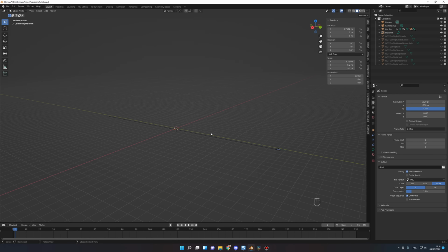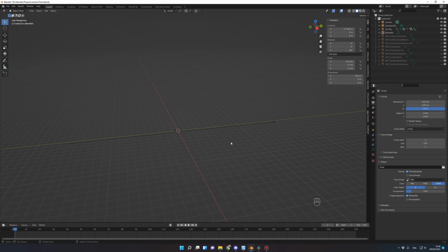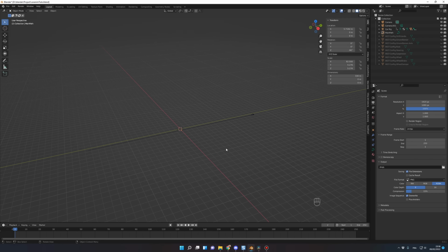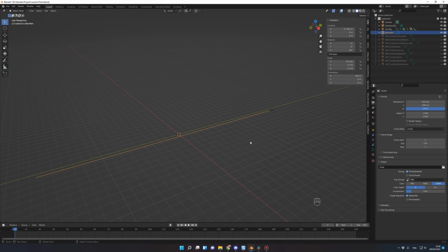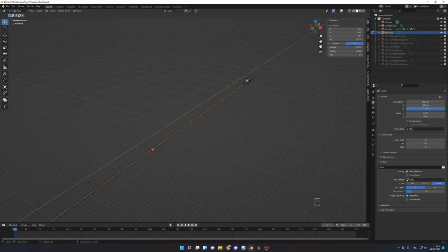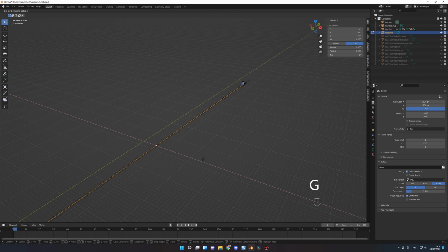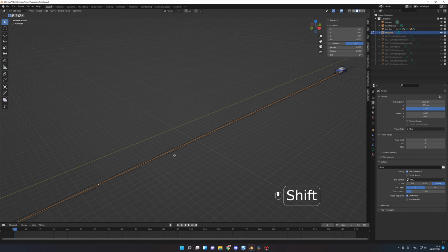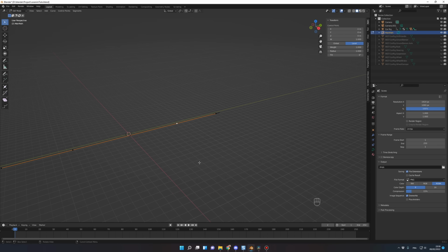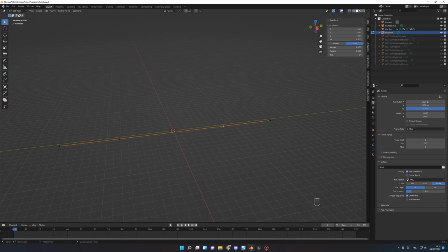The way we scale our path is not good, but I wanted to do it like that to show you a common issue that people have. If I select my path and go in edit mode, and select a control point, and move it on the X-axis, as you can see, my car is flipping around. Let me show you. Here again, look at my car. You see it's flipping around. This is a really common issue when people scale the path directly using the X dimension.